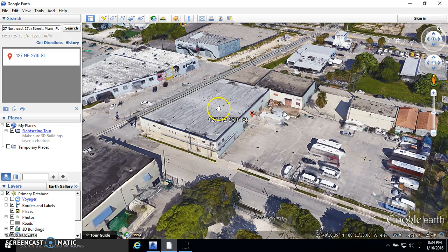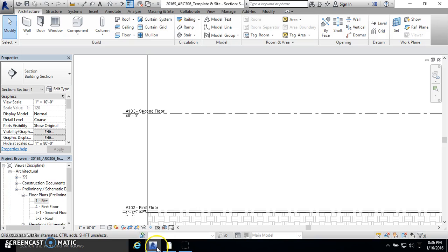So that's at 16, and the roof. Now, if you hover over the roof of this building, it says 39. It says 39 for all three. So I'm just gonna say it's 40, and I like to round it to 40, so it's even numbers. So 40 minus 16 would give you 24, I believe. So now we know that warehouse is at 24 feet.